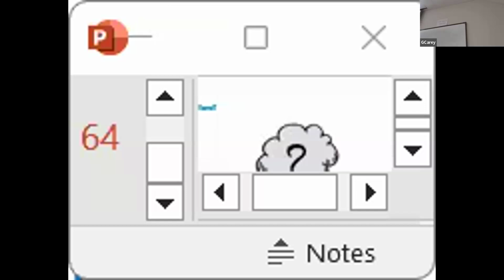So at the very beginning, when systems were designed and variable speed wasn't a player yet, this is how they probably would have designed systems. Two-pipe with control valves. At that time, it would have been a 2-way control valve, whether modulating or open-close, chillers, primary, secondary tees, et cetera, and a distribution pump. Before they had variable speed pumping, they would have these control valves.